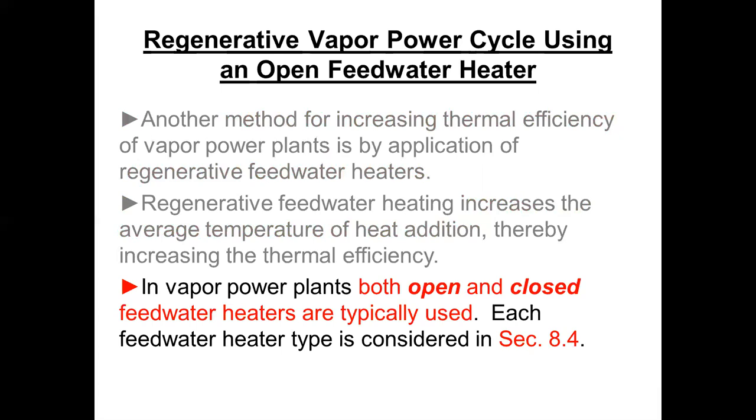An open feed water heater is called a deaerating feed water heater. The purpose of that is to strip off any oxygen or non-condensable gases that may have come into the system, probably with the makeup water. It's possible to have some air leakage into the condenser, and some of that can get pulled up into the condensate.